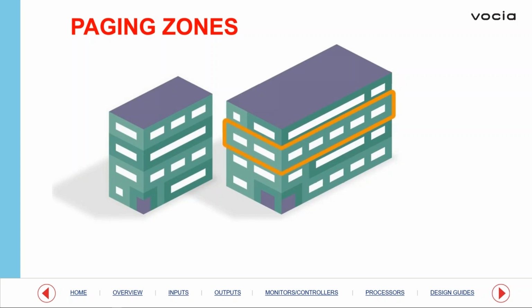And then the last piece is that, hypothetically, this particular entity grew so large that they needed to take over the entire 3rd floor. Once again, anything that was connectorized, amp channel count or speakers, we could possibly take that in as just a page code, incorporate all those zones, all those amplification channels and speaker circuits, and now all of a sudden that whole floor, 3rd floor in this case, would act as one paging zone.